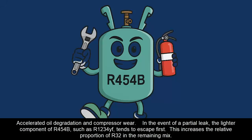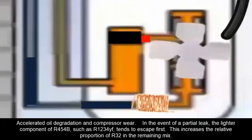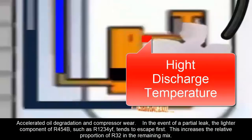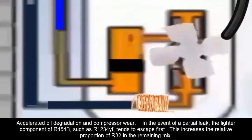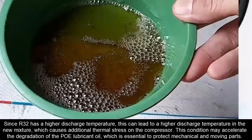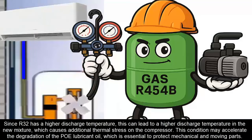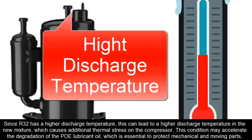Accelerated oil degradation and compressor wear. In the event of a partial leak, the lighter component of R454B, such as R1234YF, tends to escape first. This increases the relative proportion of R32 in the remaining mix. Since R32 has a higher discharge temperature, this can lead to a higher discharge temperature in the new mixture, which causes additional thermal stress on the compressor. This condition may accelerate the degradation of the PE lubricant oil, which is essential to protect mechanical and moving parts.